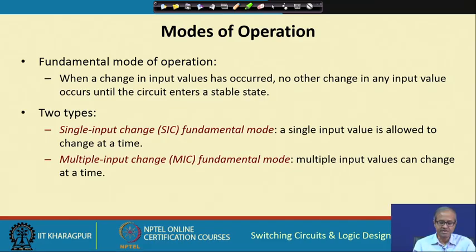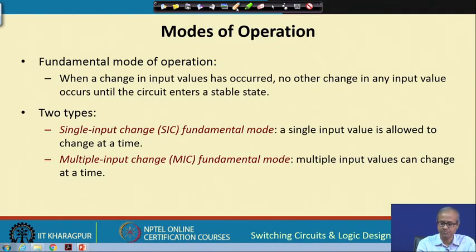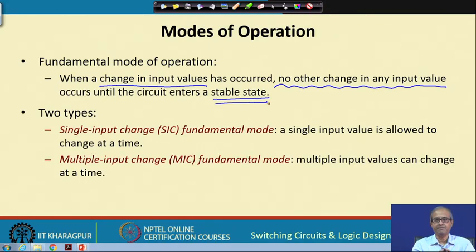Such an asynchronous circuit has something called a fundamental mode of operation that we referred to. In the fundamental mode of operation, what we assume is that when we have made some changes in the input variable, we must be very careful. No other changes in the input values are permissible before the circuit enters a stable state, because here there is no concept of clock.